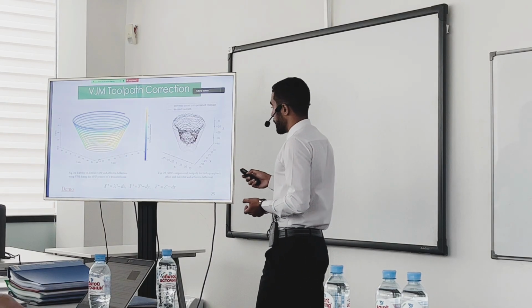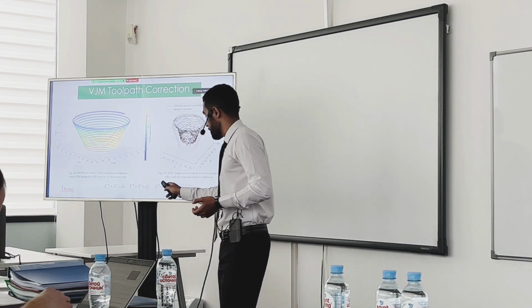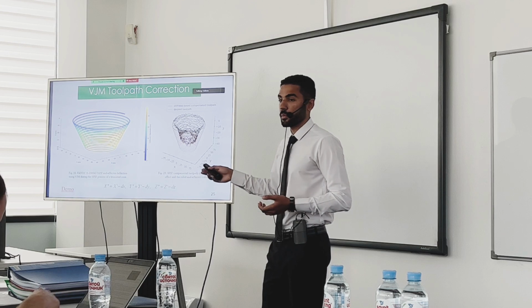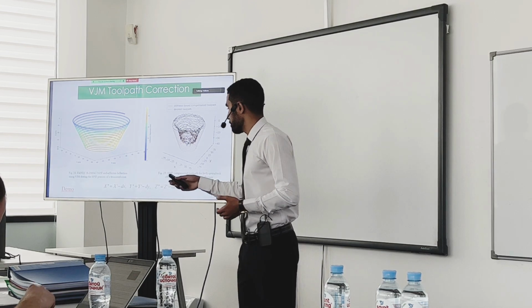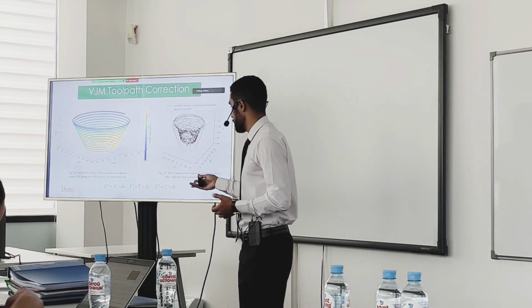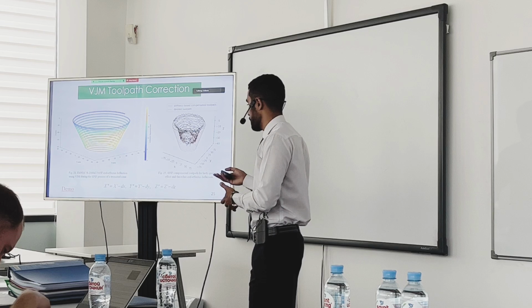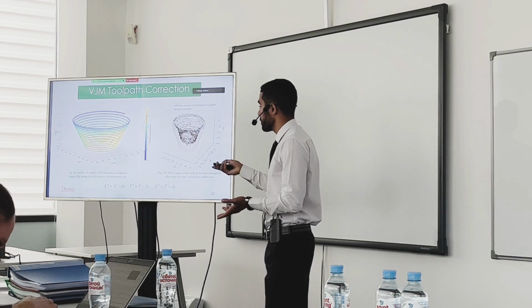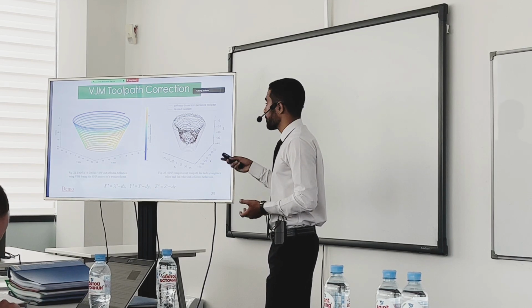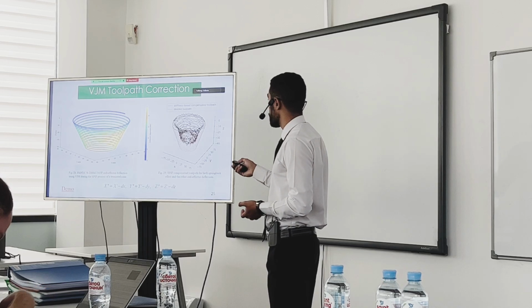Here x prime, y prime and z prime we obtain from the spring back effect compensation. So here I'm getting the new tool path out of the compensated tool path from the spring back effect. And you can see the final tool path that should compensate for both the spring back effect and the tool path deviation is presented here in figure 29.